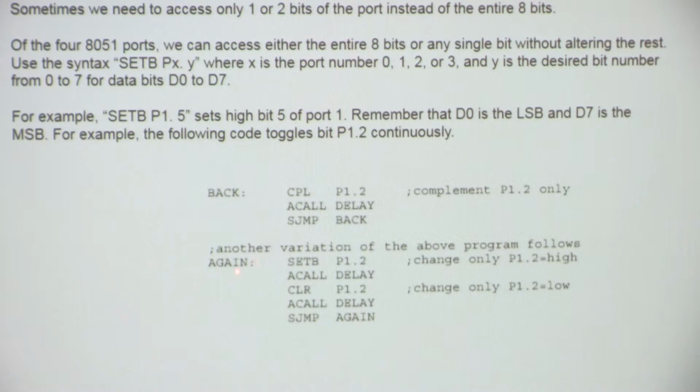Here's an example of the again program. It's just a simple delay. That's another variation of the program, but this one is the best one, it's a shorter one. Then I short jump back, and I complement it again. So can you see it's going to toggle? The time that it's going to take to toggle is obviously depending on the delay program, isn't it?